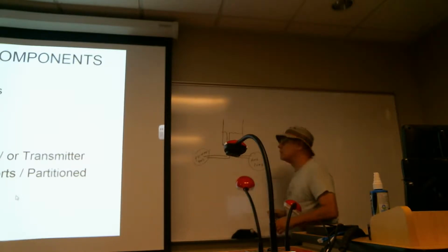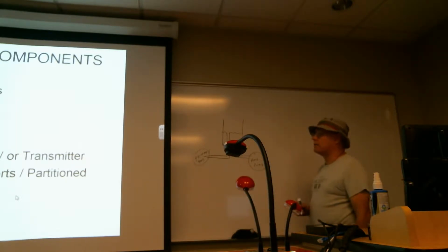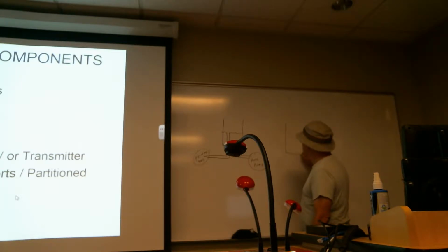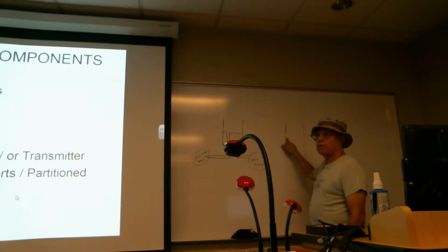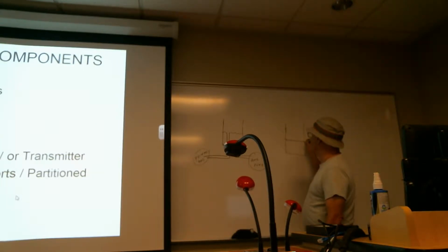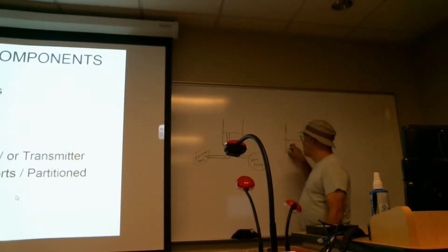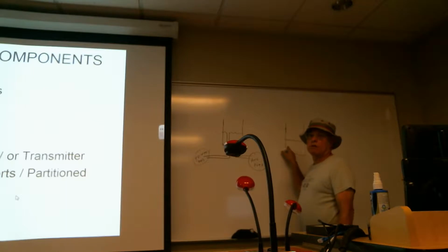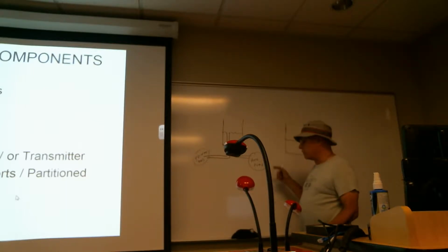Another thing that we can do in order to segregate fluid would be to have staggered ports. If you look at the wall of the reservoir, you might find two ports that are located at different levels. These would be outlet ports that feed into a pump. Maybe one a little bit higher than the other. The outlet at the top is going to feed into a primary pump, and then once the level of fluid dips below this level, then the primary pump will be starved of hydraulic fluid, and then the level beneath it will be available to maybe an auxiliary pump. So that's another thing that we can do.